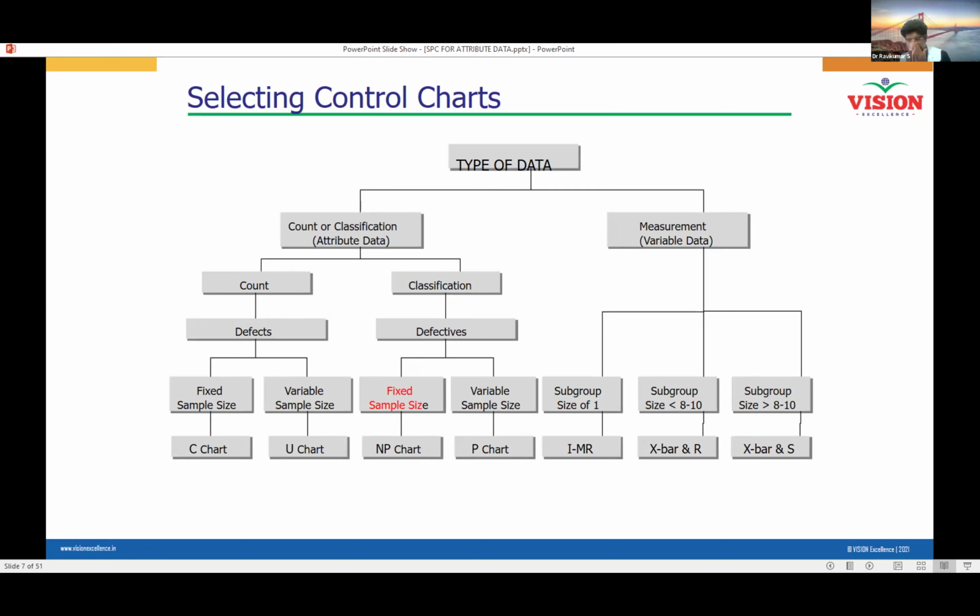So you must be aware of the difference between defects and defectives. For example, you may be having a lot of rejections. That is called defectives in your process. Suppose you want to know why the defectives are happening, then you can choose a sample of 15 days, collect the types of defects which are occurring frequently, and plot them in the control charts.